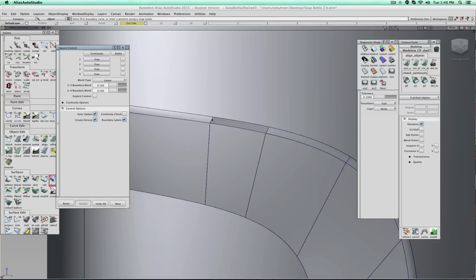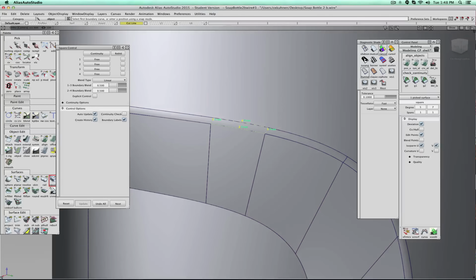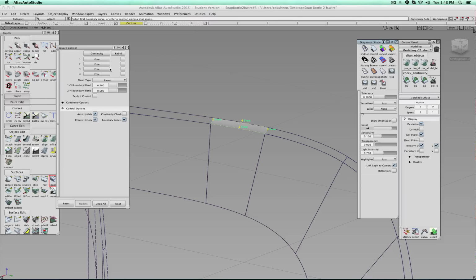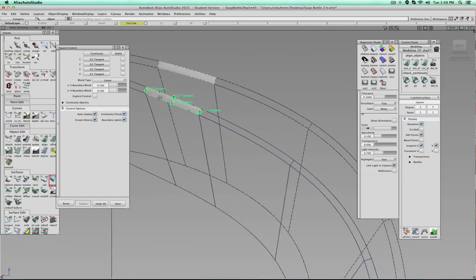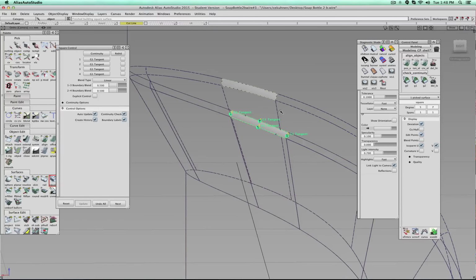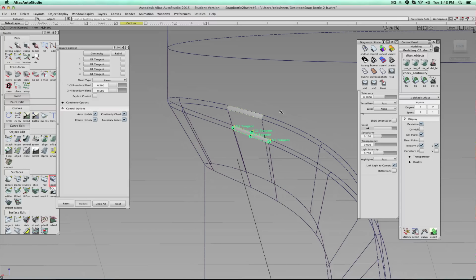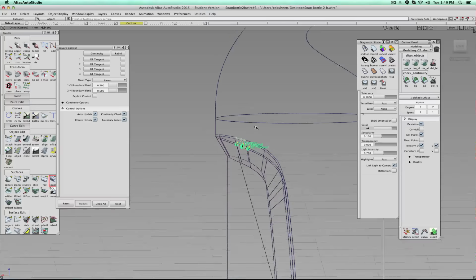And for example, let's go in with a square tool, and I think I should be able to select all squares. You see, it's a perfect match. I mean, all these edges line up, which is why it was really important. So now I could go ahead and say tangent, tangent, tangent, tangent. And technically speaking, I rebuilt the same surface, and it's all tangent as well. So this is, for example, a third way in case your grid layout is good and the align tool is too problematic. Throw it out and just rebuild some of those secondary surfaces.